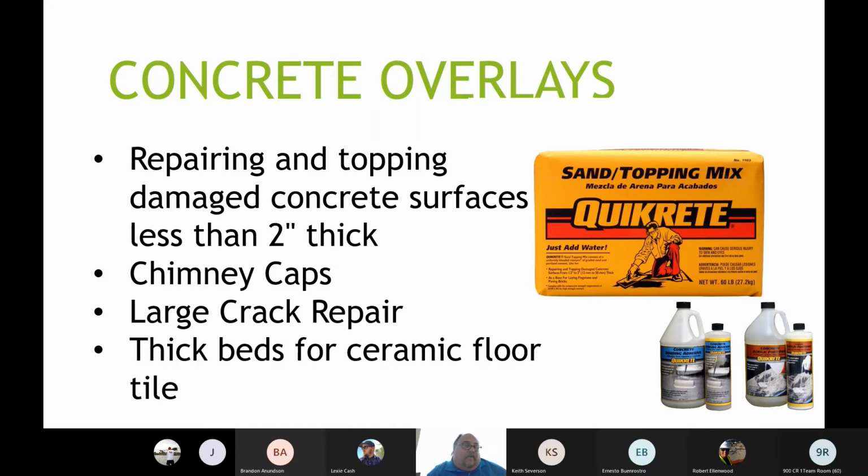Anything over 2 inches, you're going to want to use concrete anyways, so why bother with a patching material unless you're going 2 inch down, 2.5 inch down to something, and you can extend this with aggregate. You can just get pea gravel, usually about 30 pounds for a 60-pound bag, and you're absolutely fine. It can be extended. Mix in the fortifier, it makes it even stronger. Put the bonding adhesive down on the thicker applications, and now you've got a chemical bond that's 5,000 PSI.